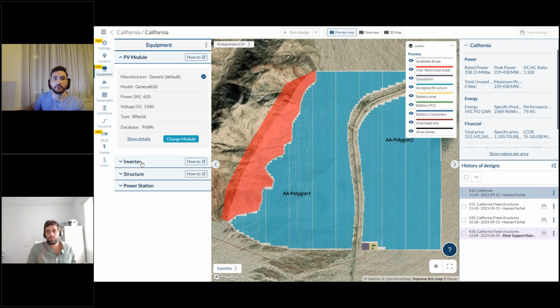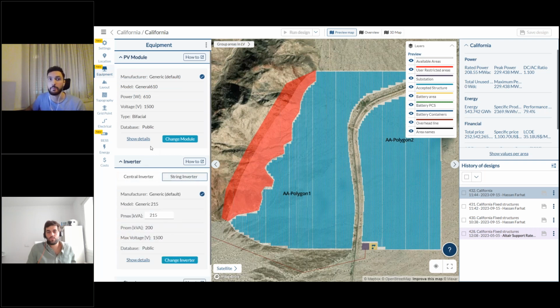For these, of course, make sure you're uploading the same PAN and OND files. It's preferable that you manually upload them, because even though you might see the same name coming from the manufacturer, sometimes some characteristics might be slightly different, just because maybe one tool has a less updated file or equipment than the other one. So just to avoid these differences, it's better to upload the PAN and the OND files manually.